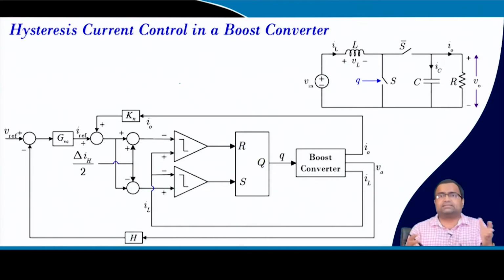In fact, we discussed that hysteresis is a more perfect solution, but remember in voltage mode, we should not use voltage hysteresis control for boost converter because of the non-minimum phase behavior. Because of the non-minimum phase behavior under step up load transient response, the system can collapse unless you put a limit on the on time.